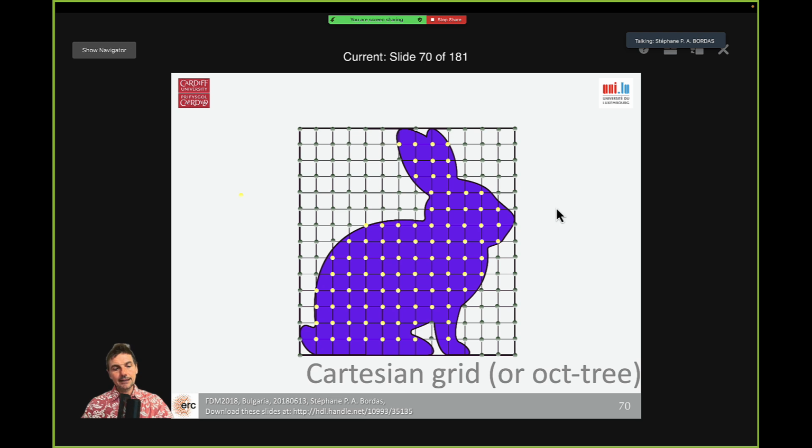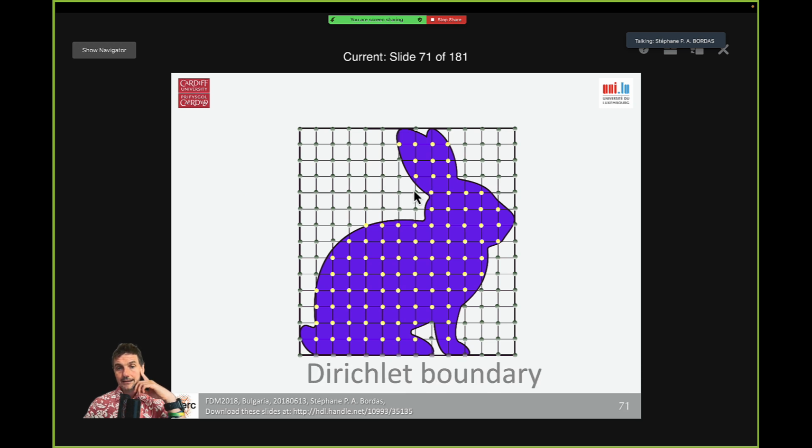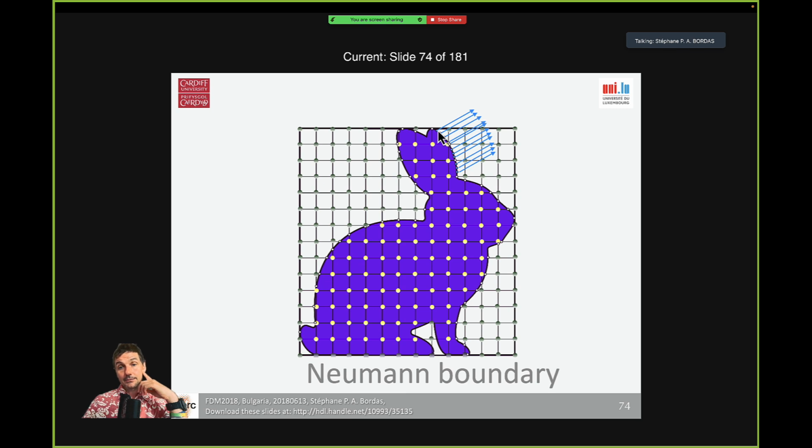And the idea would be, okay, can we simply have a general regular mesh, and can we put some points which are either in or out, and then work on imposing boundary conditions. So first we impose the Dirichlet boundary, then we impose the Neumann boundary, if you can see the points that are here at the interfaces, intersection points that I just created. Then we impose maybe the Neumann condition, so we need some more points along that surface, which is known maybe by NURBS. And what we are now able to do is to do all this for very generic problems.